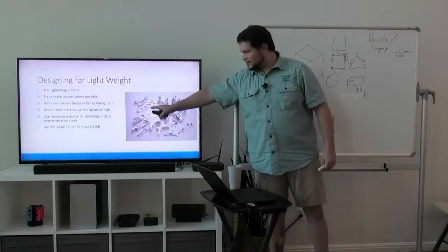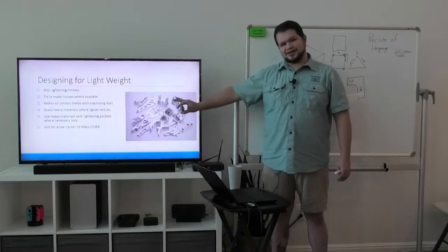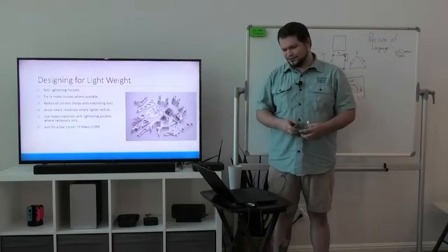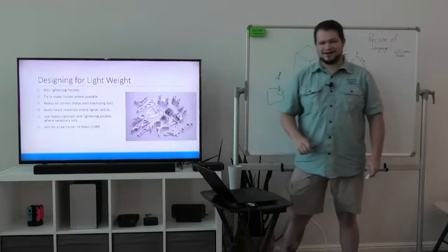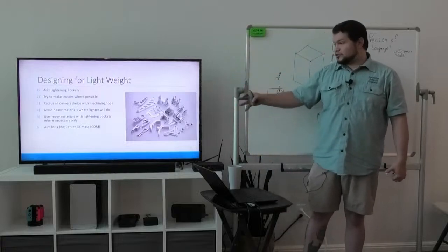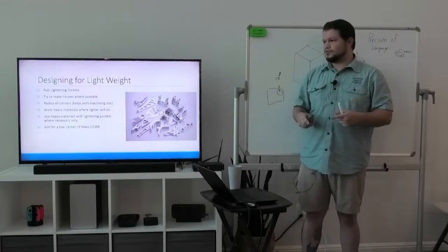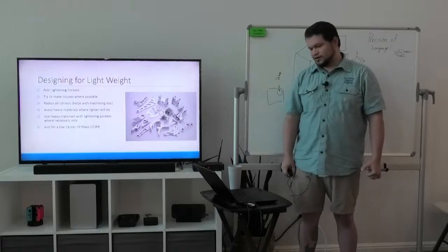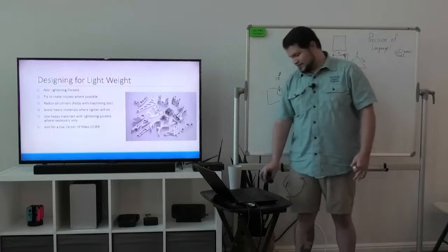When you take away excess material like this and leave behind typically a truss shape, it's called lightening pockets, and not lightning as in what strikes, but lightening as in make it lighter. So it's spelled a little differently, because you're making it lighter. You want to try and make your trusses where possible, so avoid having rectangle shapes whenever you cut away material. Try and keep it as all triangle shapes. You want to radius all corners, and this helps with machining. Why does this help with machining?